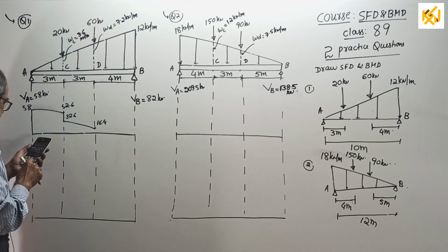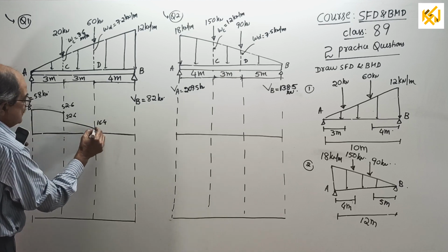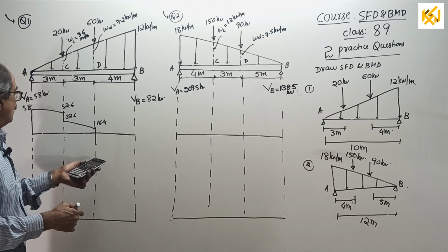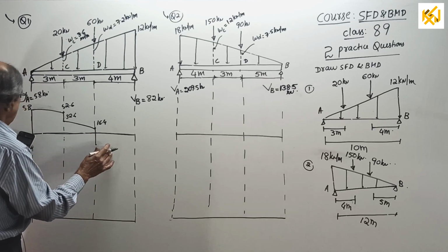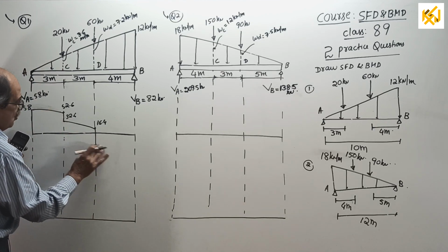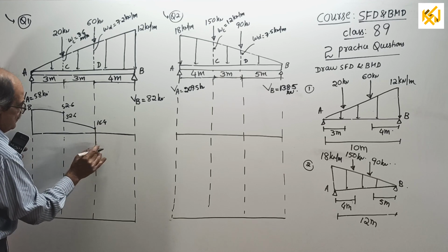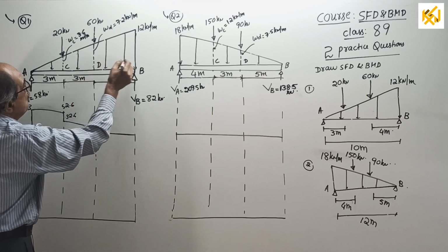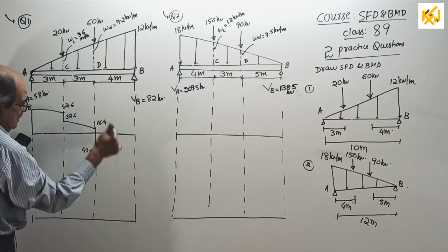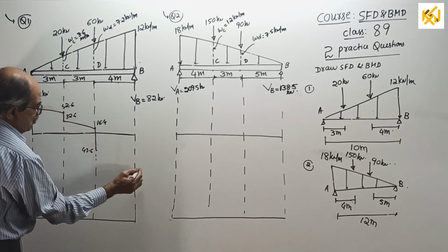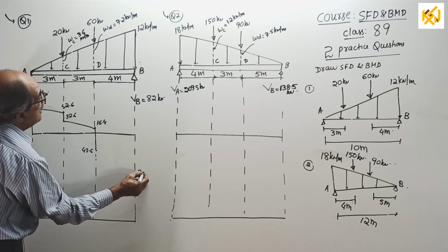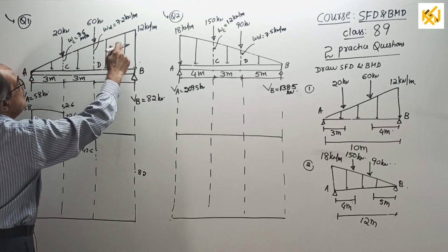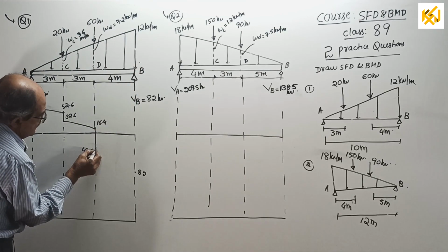Come down by 60. Minus 60. See, suddenly you can see here now, shear force diagram crosses baseline at a known point. Minus 43.6 compared to 58, little more. Minus 43.6. Okay, reasonably okay. 43.6. From here to here, again come down by this much load. It will surely come 82 here. 82 here. Again, how? As you go this way, intensity increases, slope will increase.